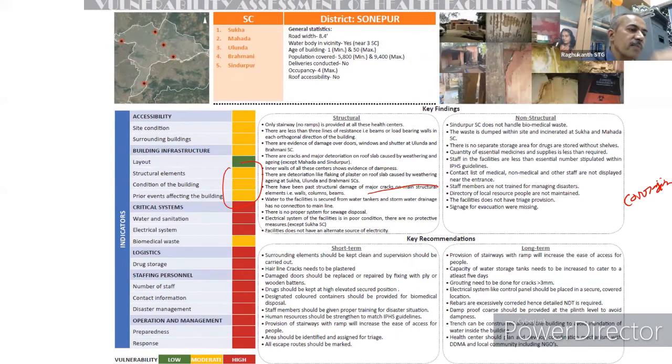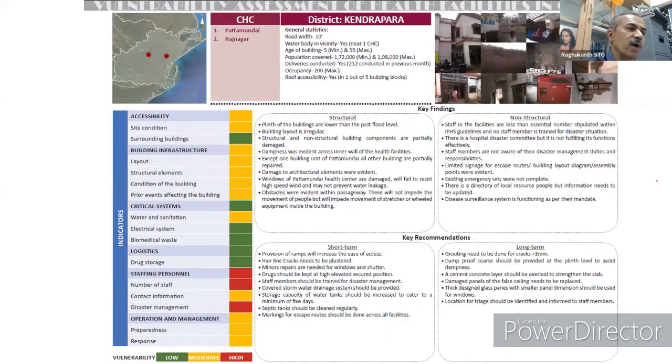So this is also another building I'm showing you. Like that, we have got all the details. Like you can see huge corrosion. This is also a hospital building. The huge corrosion is chloride induced corrosion we have seen, and some hospitals were converted to a higher use, so the loads also got changed. This hospital was constructed 40 years back. Then 20 years back, they did the alterations. They converted the old materials to new materials, and they got disintegrated also. So all these issues you can identify in this hospital building.